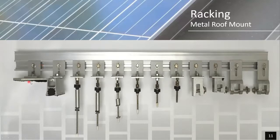So what we'll see is a flat plate with multiple penetrations like this with some sort of butyl membrane underneath. You'll see a hippo mount to go over that ribbed option. Or what you'll see are these legs and with different spacers on them depending how deep they have to go. Because the issue that some installers find with metal roofs here in Nova Scotia is they'll get strapped over top of existing asphalt roofs.